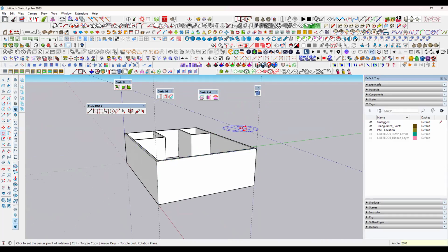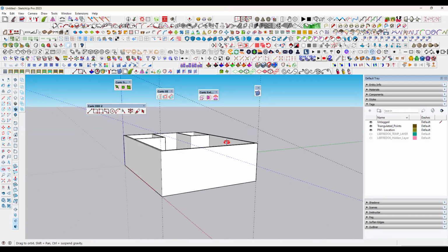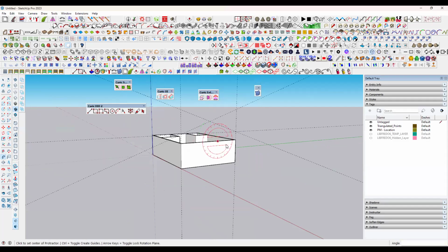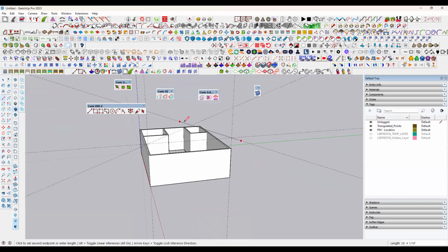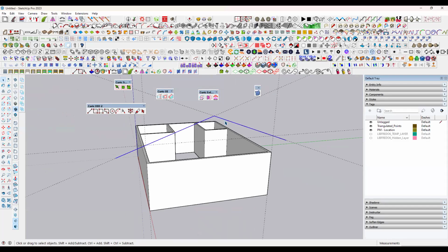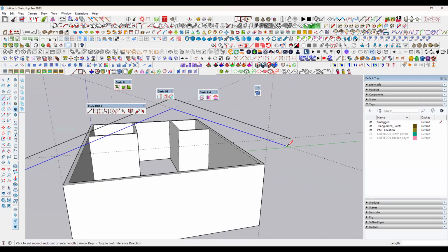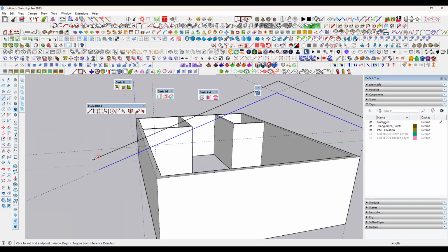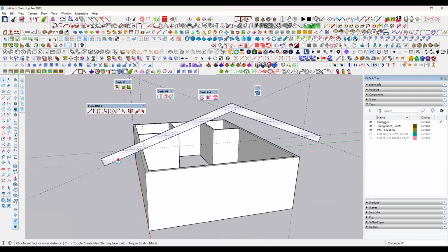Here also I'm going to use the same type of line, and I'm going to copy it here. First I'm going to take it here, complete this one. Take one more taper line, keep it here, select this one, and set this one to 40 degree. Now I'm creating a simple rectangle, the line, from here to here. Then I'm going to give an offset with the help of this. Then I'm closing the line to make it a solid here. So this line I'm creating, then I'll push-pull.